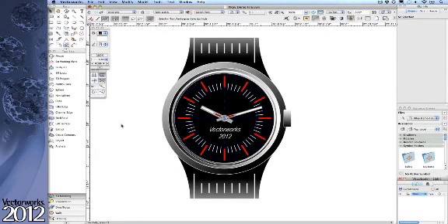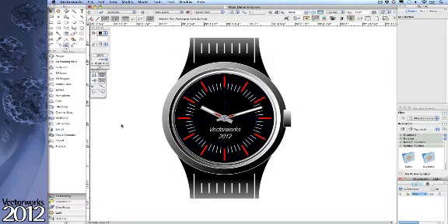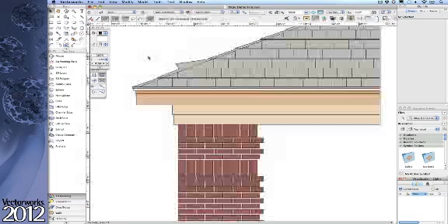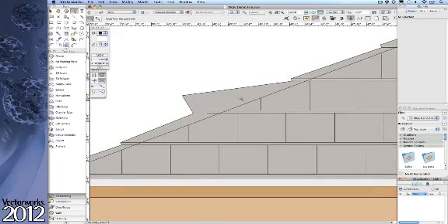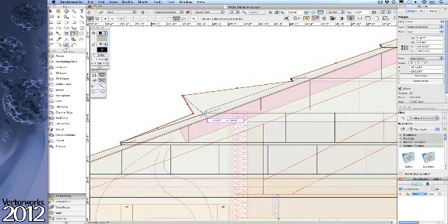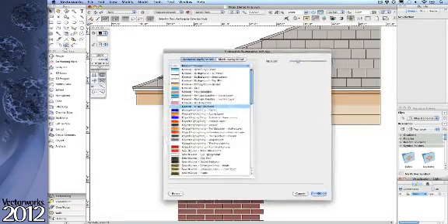Ever need to see what's behind the elements you're currently working on for alignment purposes? Well, here's the perfect tool to help you alleviate the old hide and seek. Just by pressing the B key, you'll toggle on and off fills, providing you with the ability to see what's back there. You'll be able to quickly see and accurately snap to, align, reshape, and move objects that are hidden behind other objects. The degree of opacity for this new feature is set in the Interactive Appearances settings, giving you just the look you need.